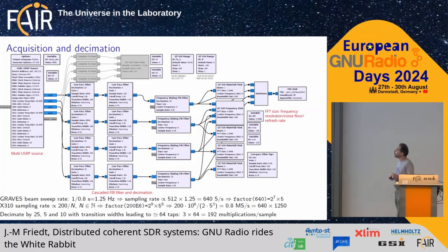So this is what the GNU Radio flowchart looks like. Be careful that if you want to synchronize multiple USRPs, you need to run a multi-USRP source, because the computer running the multi-USRP source is going to broadcast the signal to all the USRPs to synchronize them. You see that the center frequency is 56.95 because I'm using the second Nyquist zone.